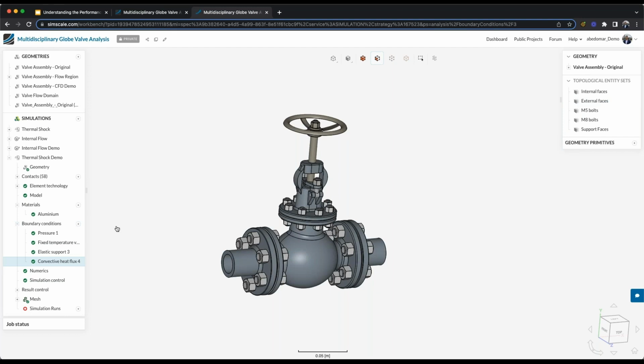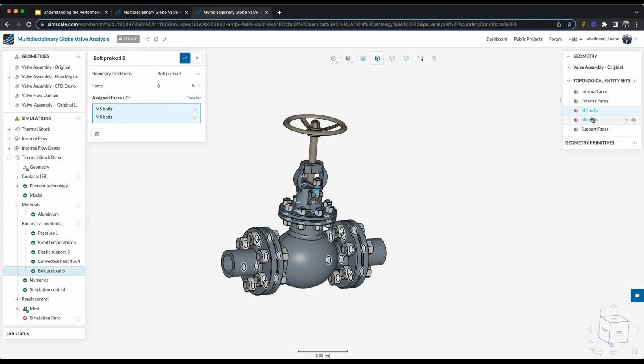One last thing I want to model is the bolt preload within the model. For all the bolts, as you would in your typical structural analyses, you're not going to hand tighten these bolts onto the pipe, especially when it's undergoing high pressures and temperatures. You want to preload it with a stress to prevent it from failing and to force the contact faces to stay together with some type of force preloaded into the assembly. You can define that within here as well.